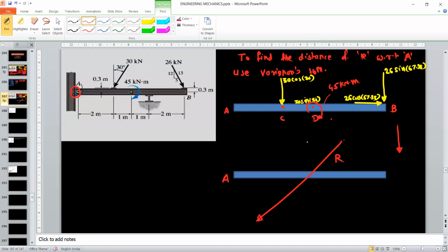So this is the resultant. I have shown this direction because I know this angle, which is theta, 84.29. Now we will specify the distance of the resultant with respect to point A. In the Varignon's theorem, for the resultant, we always assume the perpendicular distance. From point A, just draw one perpendicular on this resultant line or line of action of the resultant.